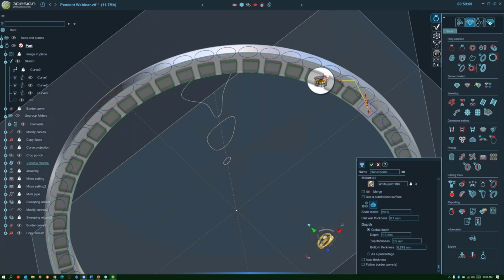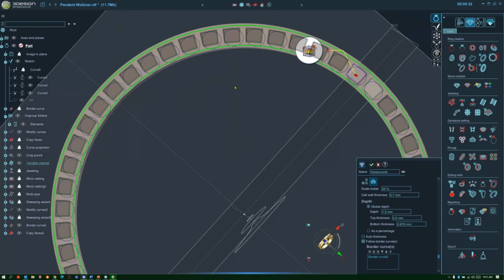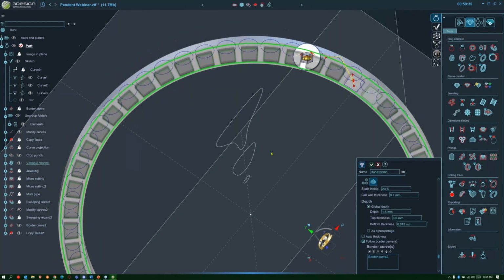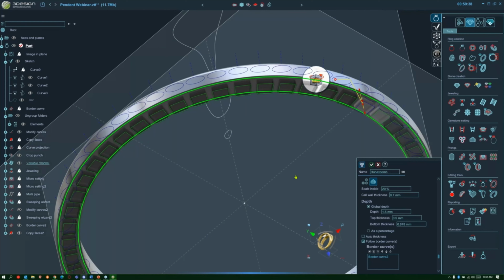Now because I use those border curves, it's going to also have 0.7 on the outside as well, where the borders are. Okay, and to really make sure the angle and everything matches what I want here, I'm going to have it follow border curves as well. Okay, and you can see now they're even more precisely centered in there. So I find that's always the trick there, is to use those border curves as guides to shape these automatically and constrain things. You get much nicer shapes.